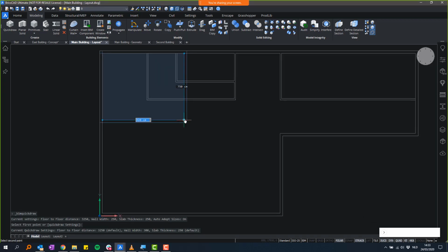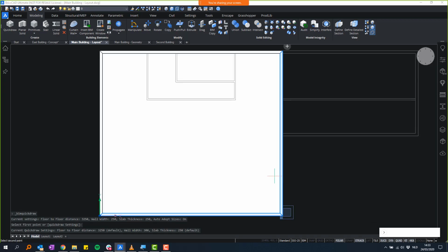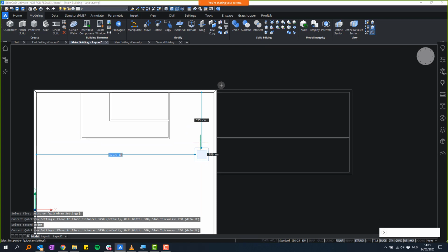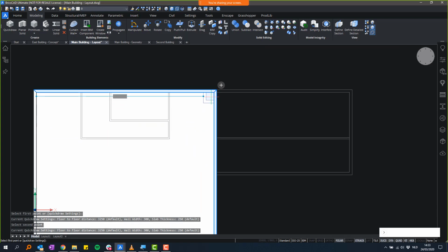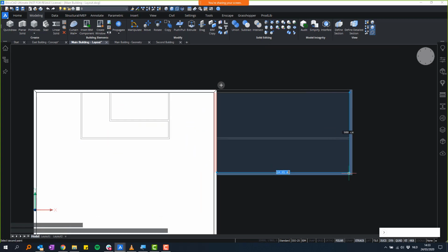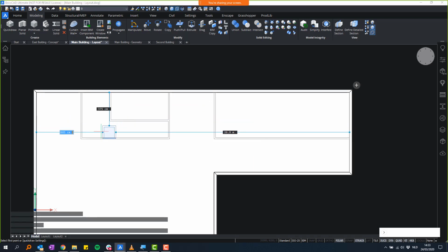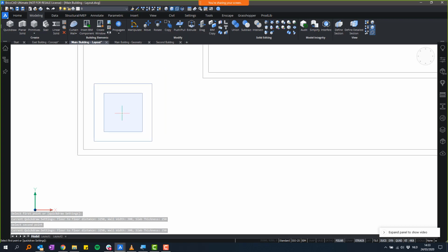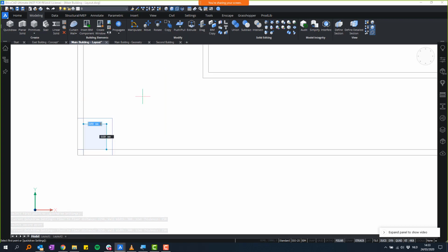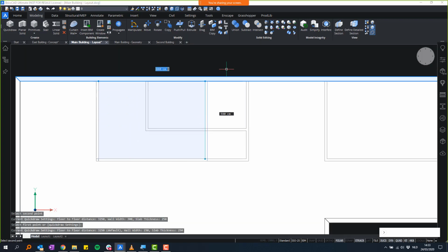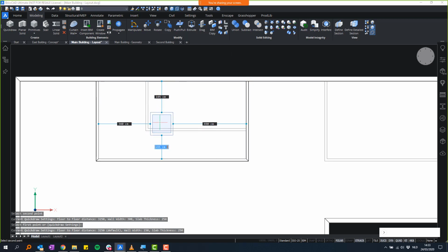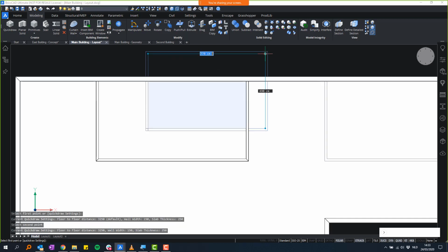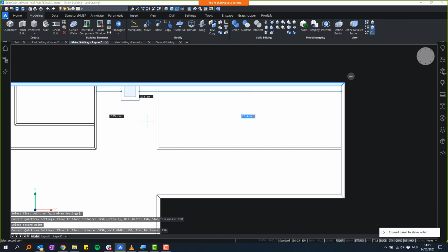It allows me to very easily create slabs and walls based on 2D or 3D geometry. You also see that the thickness of my cursor adapts to the lines here, so it intelligently interprets these lines as walls, which makes it easier for me, of course, to model this building.